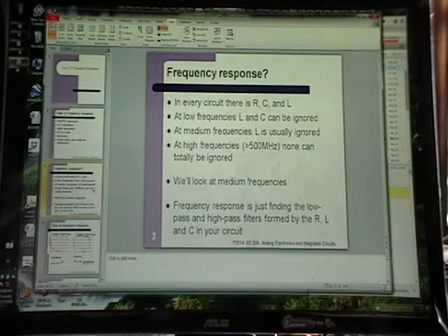And as mentioned, every time you draw a wire, every time you use a transistor, you have capacitance. Every wire has resistance, every transistor has resistance. So even if you have no intention of putting R's and C's in your circuit, you end up with R's and C's in your circuit. Inductance is the same, except it doesn't tend to be a problem until really high frequencies.